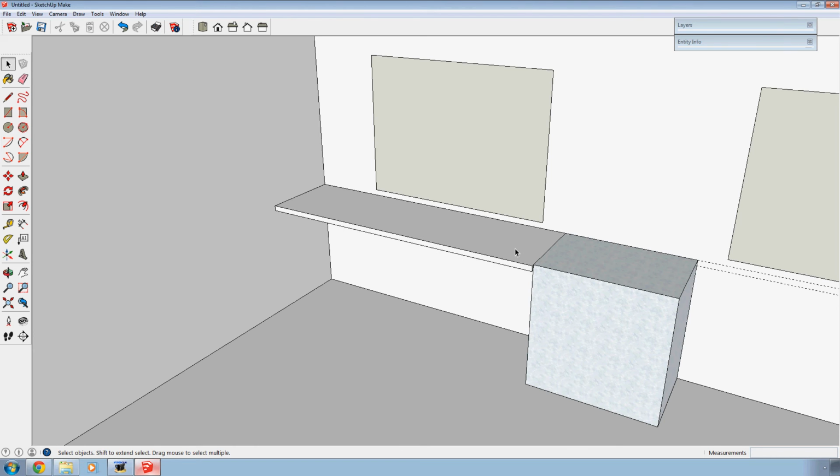Quite often, when you go around a kitchen design and you measure this and that, if you find a strange number, then there was some kind of mistake made. Virtually everything that I'll be doing will be to the nearest 5 millimeters.